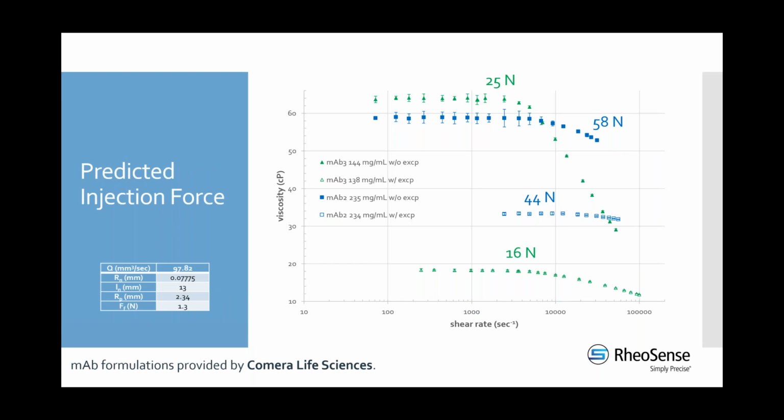Okay, before we do a more broad analysis, let's go back to those curves that I pulled up before, where we were seeing that the plateau value was nearly the same, but the thinning behavior was quite different. So do we really need to do any kind of more extensive analysis, or can we get away with just doing a viscosity measurement at 1,000 or 2,000, 3,000 and use that?